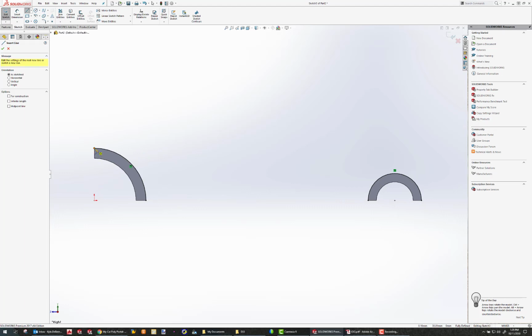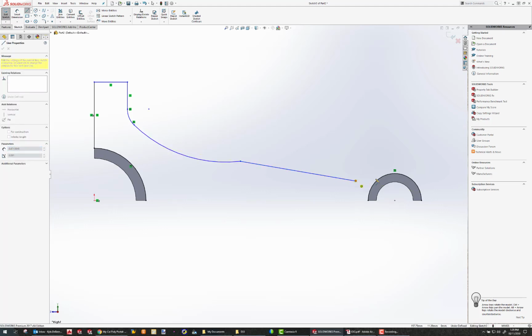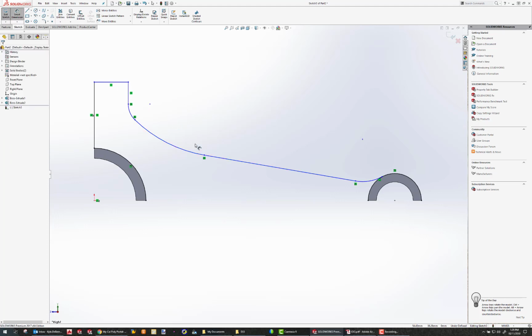Now I'm going to do a nice rough sketch of what I'm trying to do here. So there's my 2 arcs that are not defined yet, so let's not worry about that. Just kind of pencil them in. This comes down at that angle, and then I got another arc coming into there, and these lines need to be tangent, and I'm going to start putting dimensions.